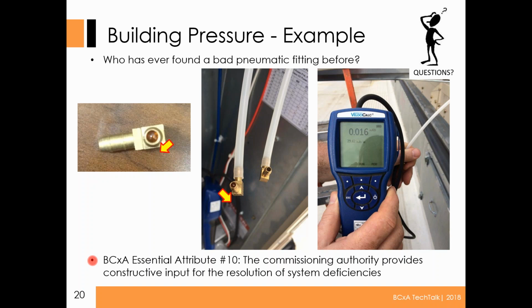And what you can see successfully at the very end was our TSI test instrument showing 0.016 inches H2O water column, and that we were finally getting a positive pressurization. So from that device right there, the TSI, we were actually measuring and teed into the tube that goes all the way down to the lobby of the building. This was a multi-story building, so we were measuring what the system was measuring simultaneously. So that's how you're going to test this.